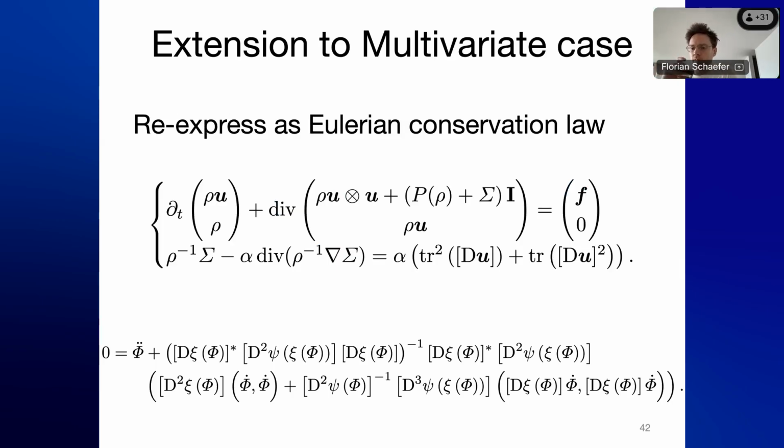Okay, so this is the geometric origin of where this equation comes from, right? I want to briefly mention that if you have, let's say, an energy equation or other stuff going on, the general rule is just to add the sigma to the pressure wherever it appears. But now I want to take a bit of time to try to relate this to something like adaptive viscosity that you might be more familiar with.